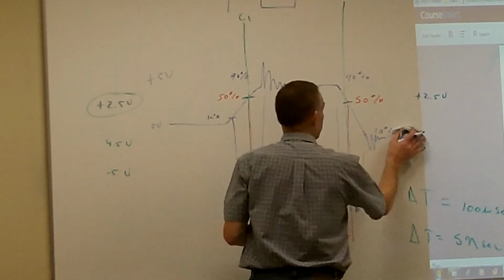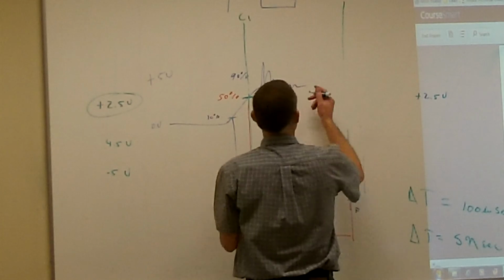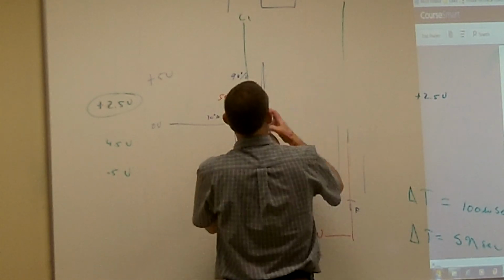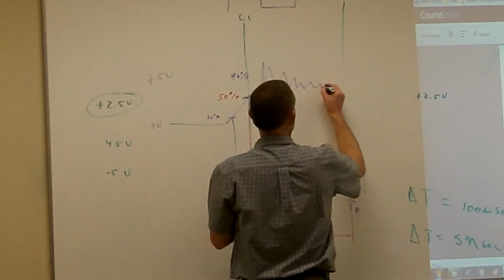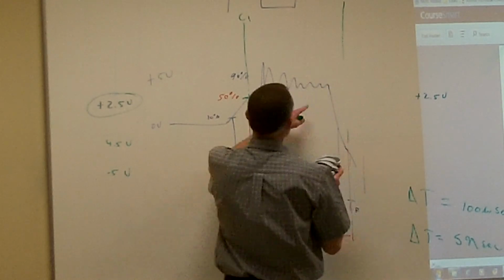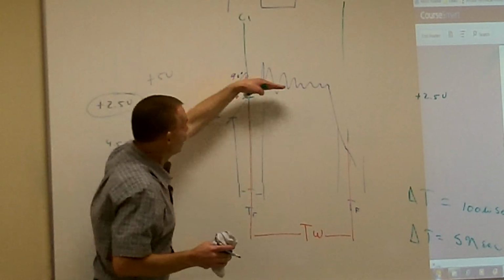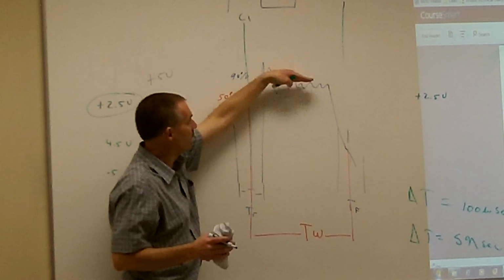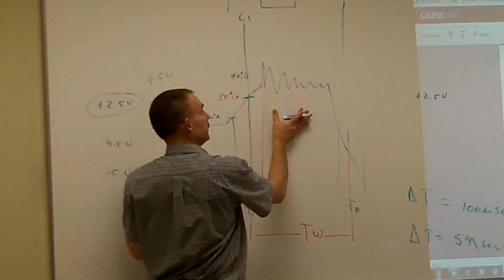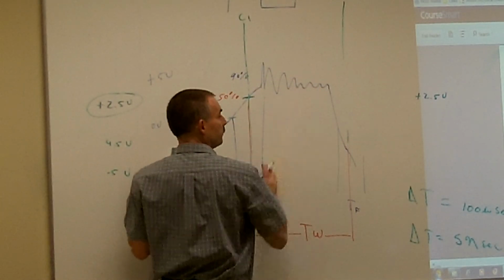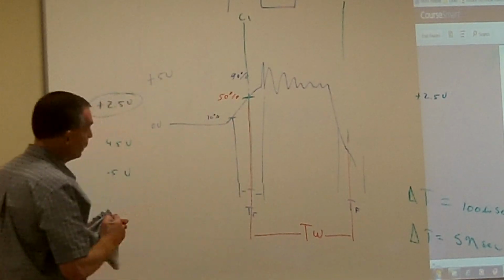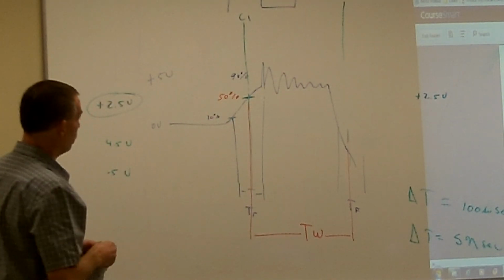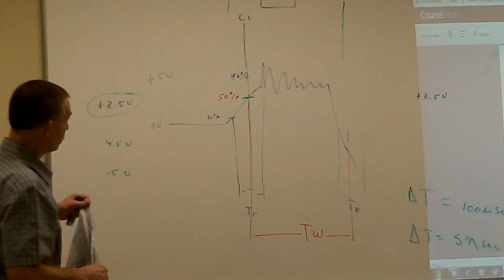Well, sometimes that stabilization doesn't even happen until it gets to the end of the thing there. All of a sudden it goes like this, and then all of a sudden it drops down. So then it's really hard to know where the heck is even my 5 volts. I don't even have a nice straight line. And so you're going to see this, and this is what we call our ringing. And you'll see that when you go ahead and do your measurements on the function generators.